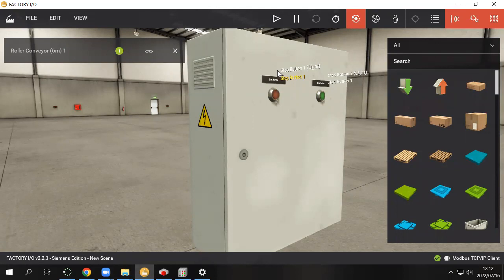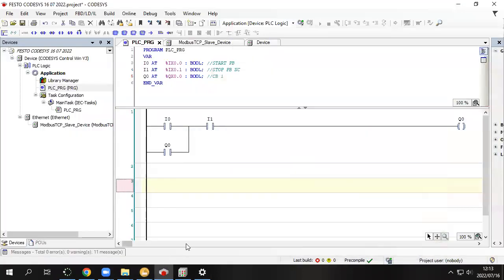Because the normally closed switch as a physical switch, you connect it with the code that is normally closed. It means that it will turn off on that code. But if you connect it as normally closed, that code will see it as on, and then it will allow us to run the program. You will see the moment we put a sensor.